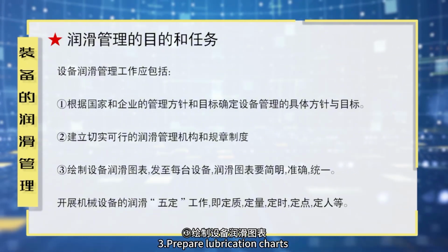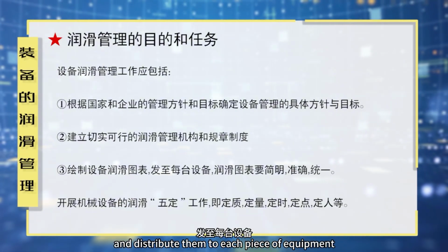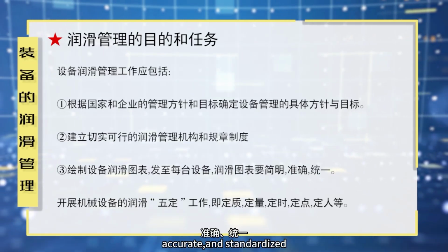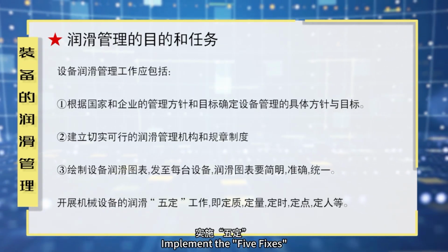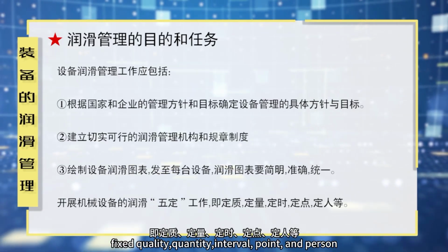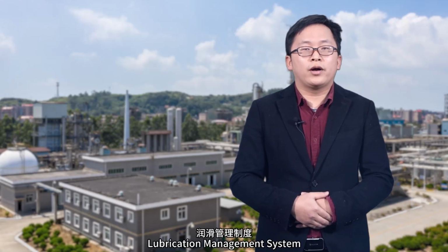Third, prepare lubrication charts and distribute them to each piece of equipment. Lubrication charts must be concise, accurate, and standardized. Implement the 5 fixes for mechanical equipment lubrication: fix quality, quantity, interval, point, and person. Part 2, Lubrication Management System.